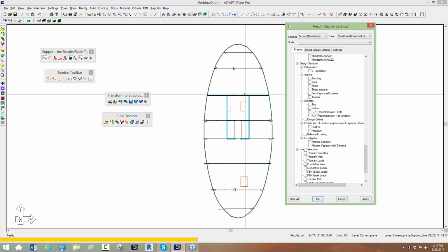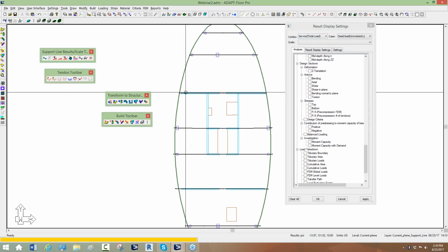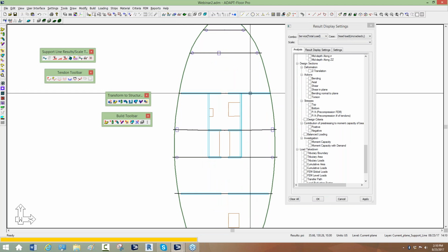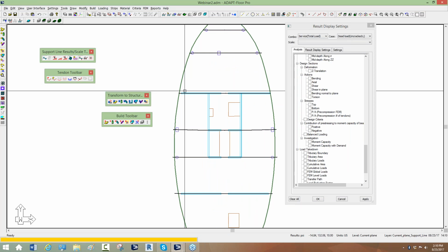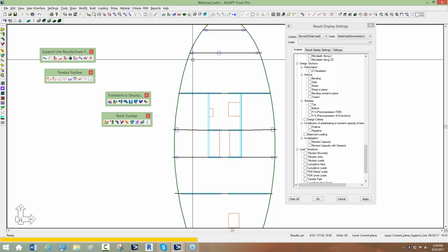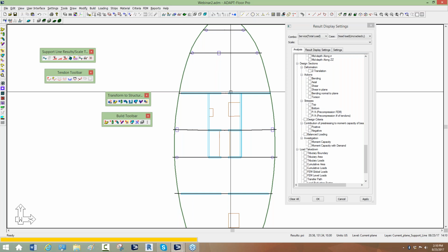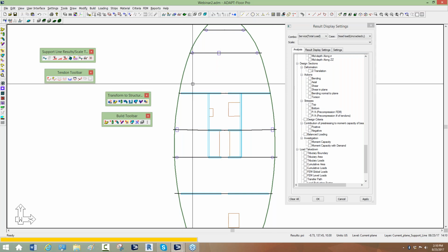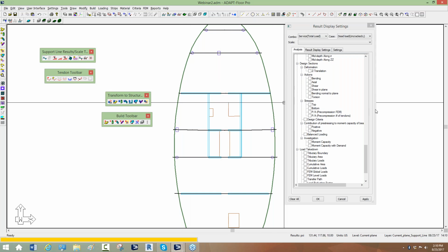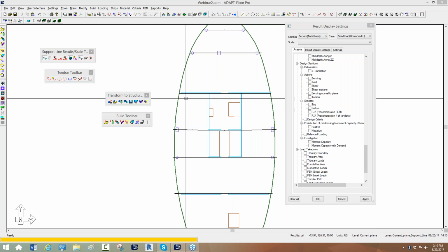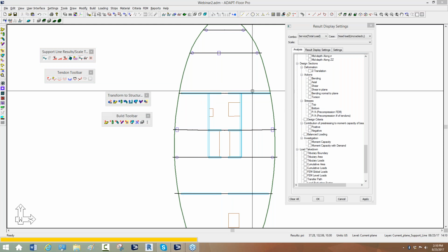Okay, so I realize there's been some discussion on adding tendons near walls. We will add tendons near walls. Obviously, it's a judgment. If you feel you don't want to add tendons near walls in a real design, that's up to the discretion of the engineer. But we've seen it done both ways. So we'll add tendons to this zone of tributary for pre-compression purposes, assuming that we're going to have detailing that considers and allows the slab to shorten.